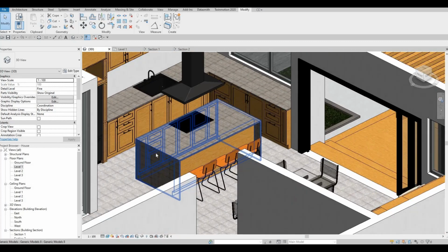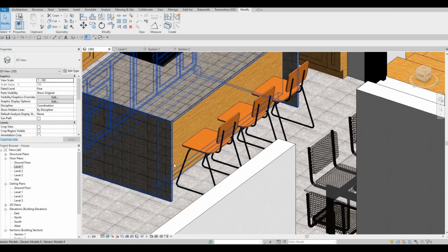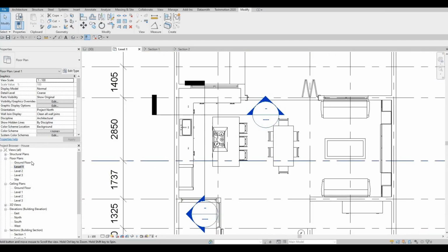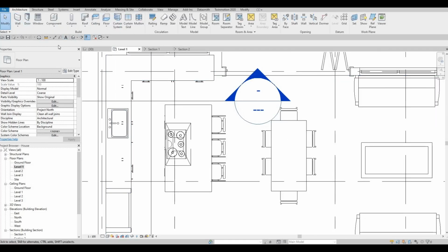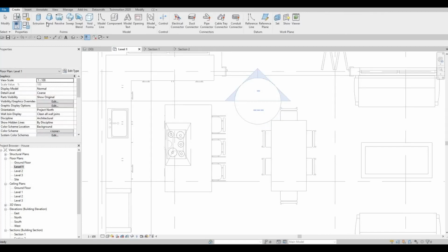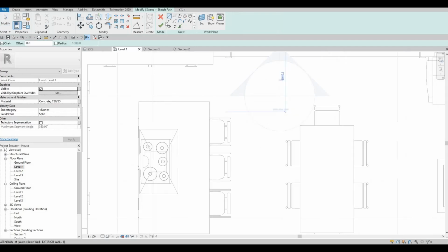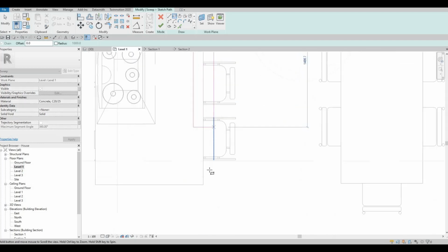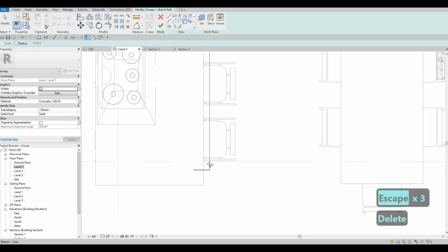And what I want to do next is to add maybe those knee rims here. So what I'm gonna do is go to level 1, and model in place, generic model, and I'm gonna do a sweep, sketch path, and let's just maybe create this first, and then delete this, and then fillet arc here.